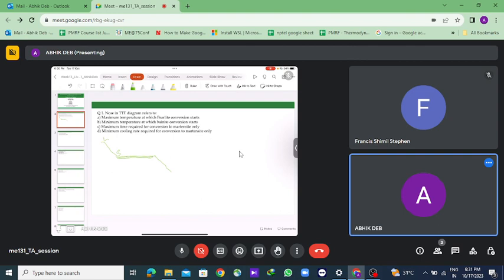Okay, sir. So by this diagram, will the pattern include only the last part, or will it include that latent heat? It does not include the latent heat part. It will be taken care of by the riser only. I mean, L2S and S2S, the entire thing will be taken care of by the riser, and when it has completely solidified, from solid to room temperature, whatever shrinkage happens will be taken care of by the shrinkage allowance.